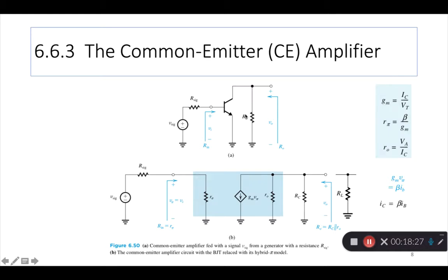And you know that the collector always has an RC, the collector resistor, to set the bias current. So the voltage output appears across the collector, but also across the RC, and actually across RL also, because that tends to be in parallel in most amplifier configurations. So I show the RL also.